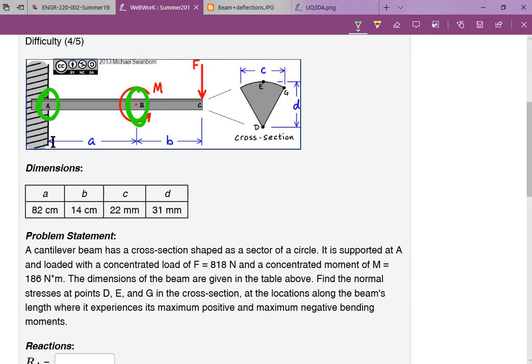You would have to draw the shear and bending diagram to be sure of that, but you can kind of look at it and tell. That's how you would know where the maximum positive M and the maximum negative M are located. Negative M at A, most positive moment at B, and different moments in between.